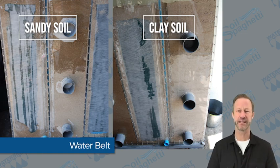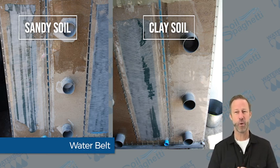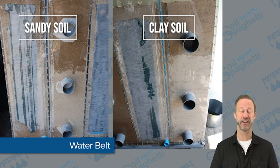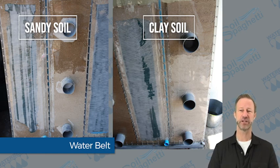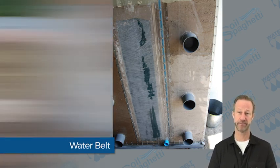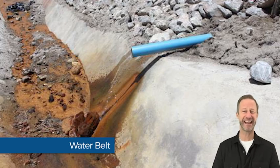In both cases, there's no water discharge from the pipe solution until the water reached the bottom of the container and the buildup of pressure was enough to force the water out. The Waterbelt solution produced a discharge as soon as the pore space saturation in an area reached 100%, even though the water penetration in the profile was at an early stage. Waterbelt is the only effective solution to address the buildup of hydrostatic pressure. A Waterbelt assembly installed vertically can collect seepage through earth dams and help prevent saturation of the soil in areas surrounding the dam.